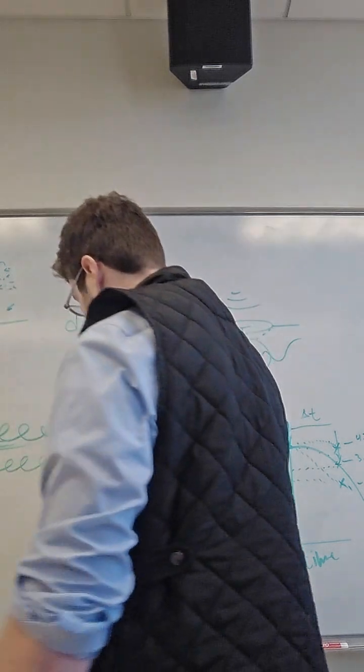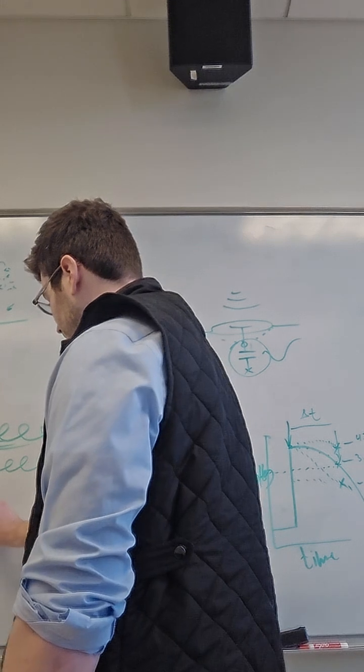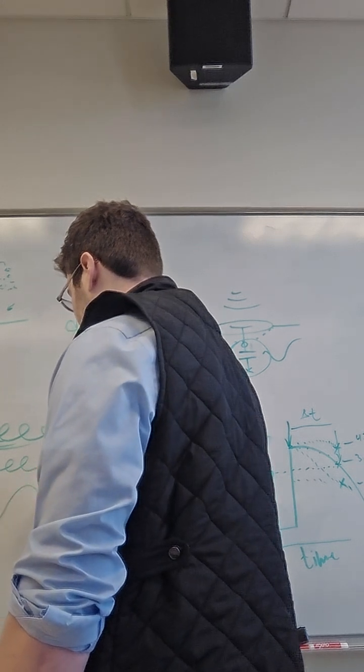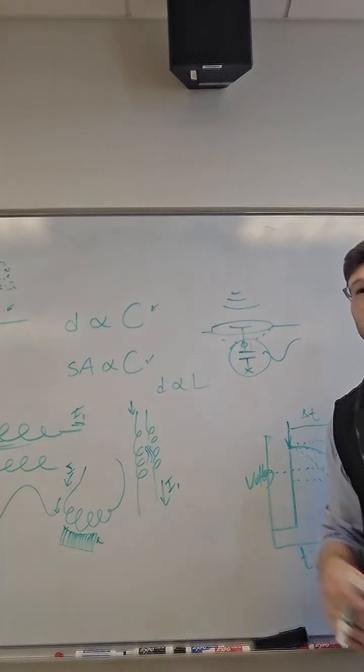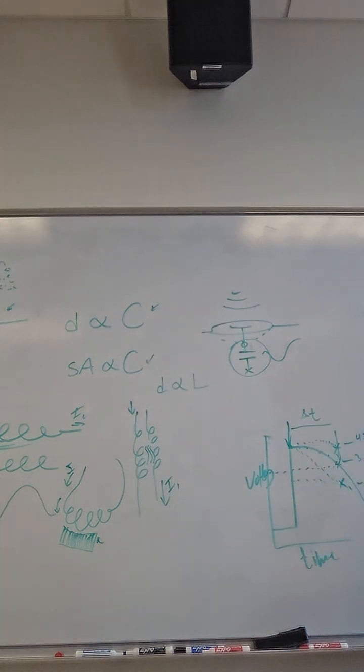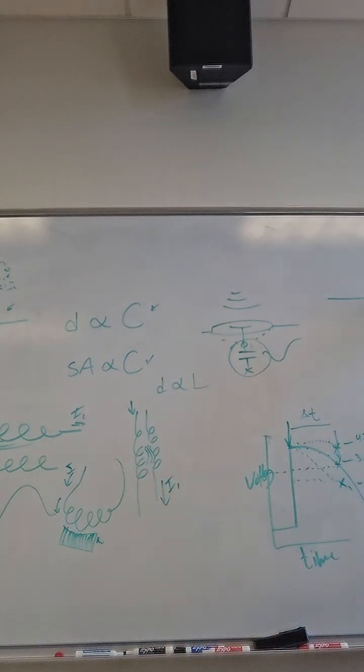Okay, so the presence of that metal, we could see as a signal, right? As a rise and fall in inductance. And then we can change that inductance to a rise and fall in voltage, and now we get metal detection. The other practical example that I see all the time, I think about it every day when I'm driving, is that sensors that can tell when you're stopped at a stoplight are based on induction.